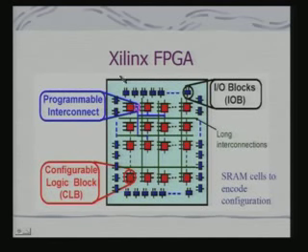So, if we look at this, this is one FPGA; there are various manufacturers. We are looking at a Xilinx FPGA organization. So, this is exactly what you have got. You have got your configurable logic blocks. These are your programmable interconnects. So, how these will be connected can actually be programmed. And these are called long interconnects.